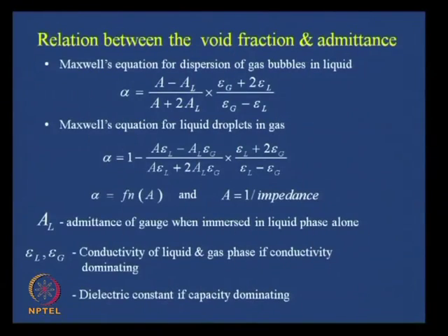So, the thing is we find that even for dispersed flow, when the dispersing and the continuous medium are interchanged, we have different relationships, and definitely totally different relationships will be there when we are having dispersed flow and when we are having separated flow. Even for separated flow, the same relationship cannot apply for stratified cases and annular cases.